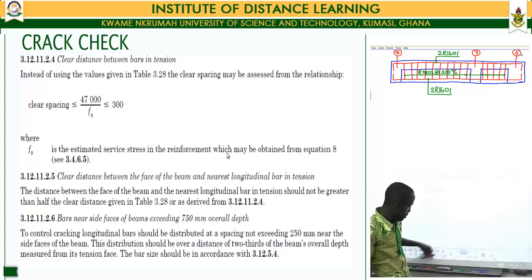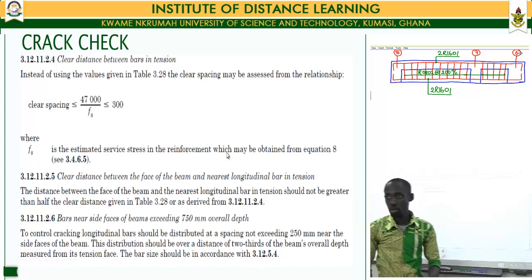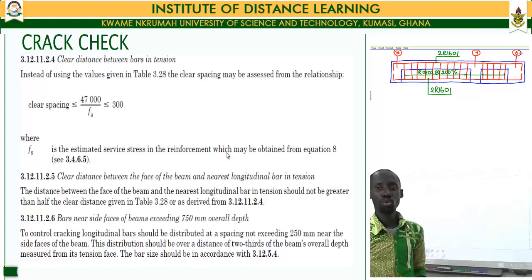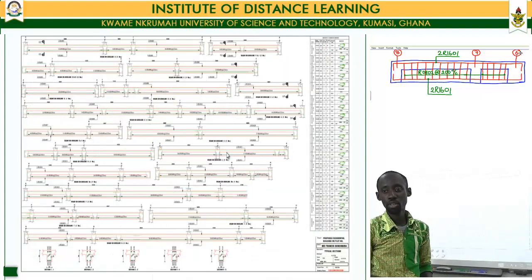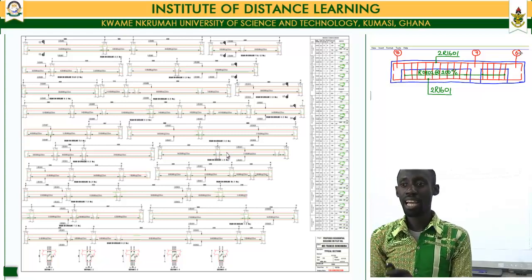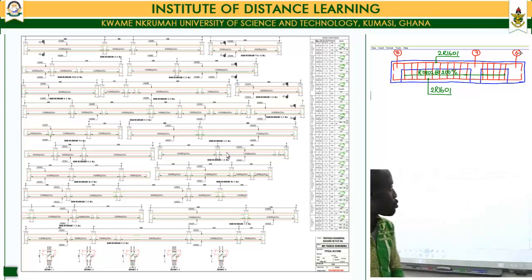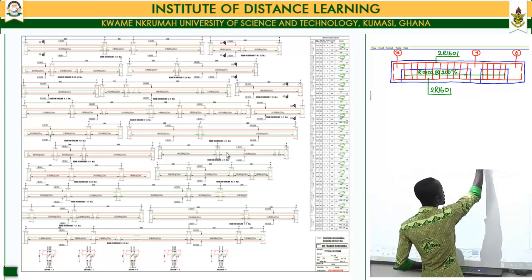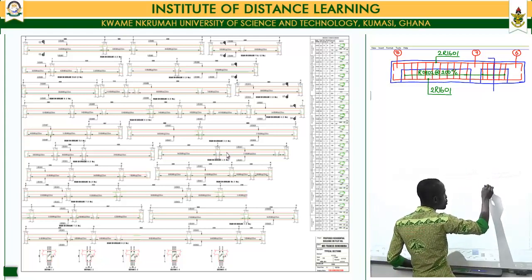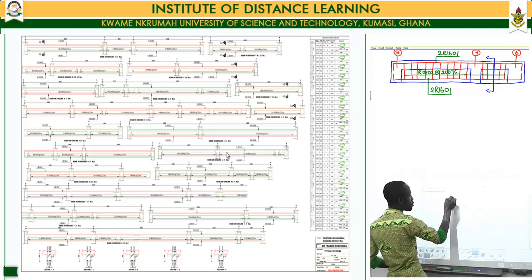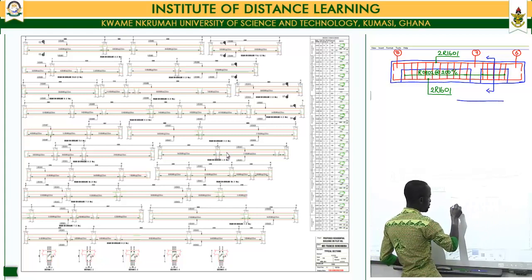So then in a nutshell, this is how my reinforced beam after the design would look like. Now applying this to all the beam sections in the building will yield us a reinforcement schedule as being displayed on the board. And this is the set of drawings that would have to be sent to the site for construction. So having come out with a plan section view, we now take a cross section through the beam and show how the cross section will also look like.